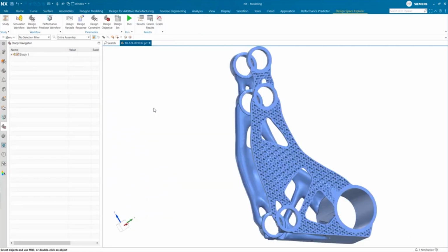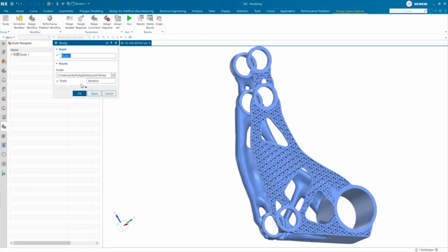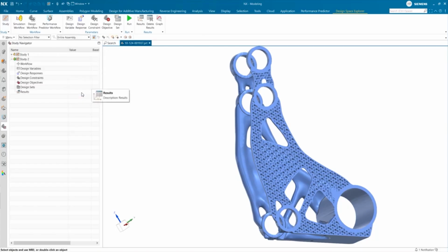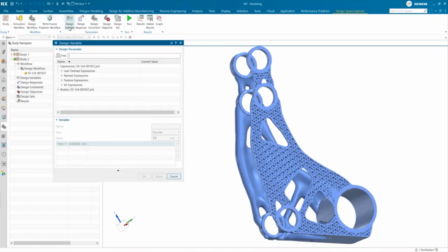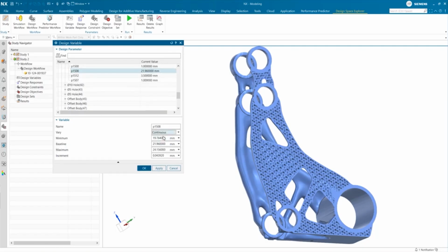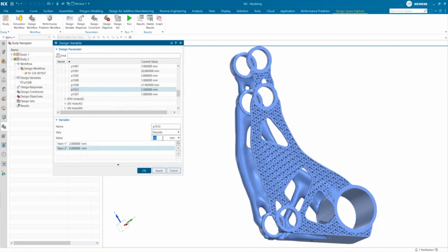We can optimize the design further with another AI-enabled tool, Design Space Explorer. This add-on rapidly iterates through different design variables, simulating performance to recommend optimal configurations. We'll use it to lightweight the gyroid structure even more. First, we choose the TPMS thickness and cell size as our variables. The maximum and minimum values are based on the 3D printer's requirements for accurately printing self-supporting structures.